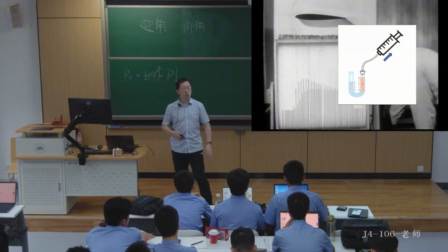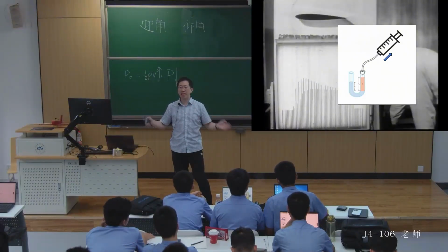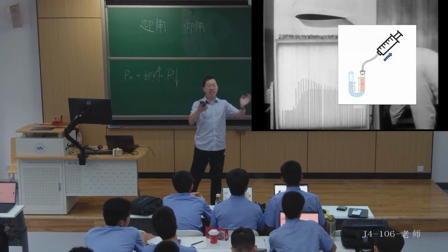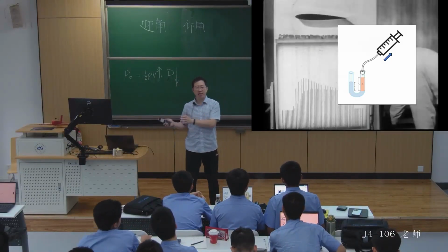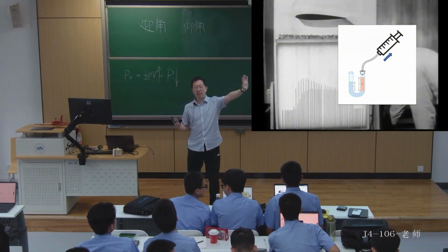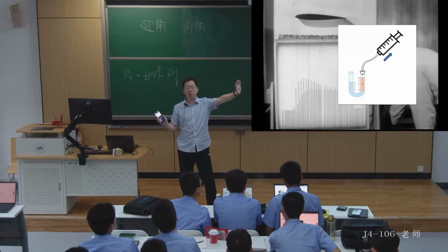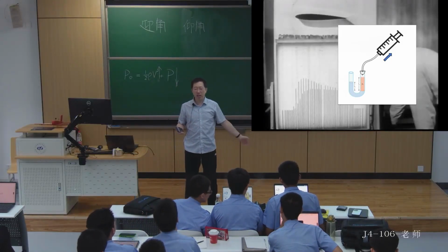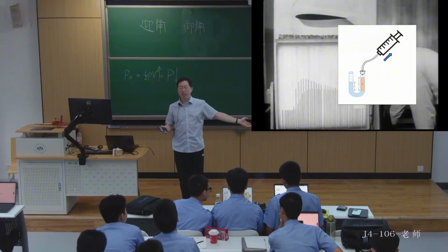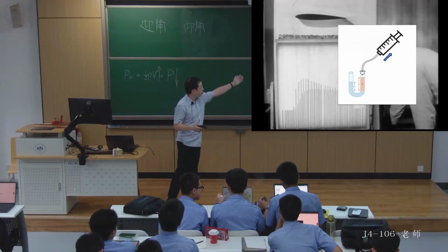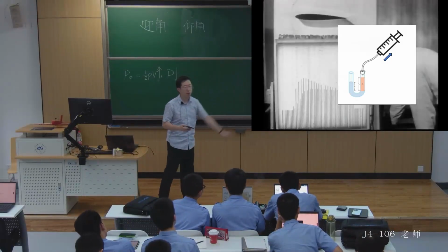We say the pressure inside the aircraft is what kind of pressure? It's the pressure of still air, right? And the pressure corresponding to suction, what is it like? Compared to still air, it's lower, right? The pressure outside is lower, and the pressure inside is higher. So if the skin panel isn't firmly attached, what will happen? It would just burst open immediately, right? It gets sucked out, so that's what we call suction. All right? Now let's take a look at how the pressure on the surface changes as the angle of attack changes.